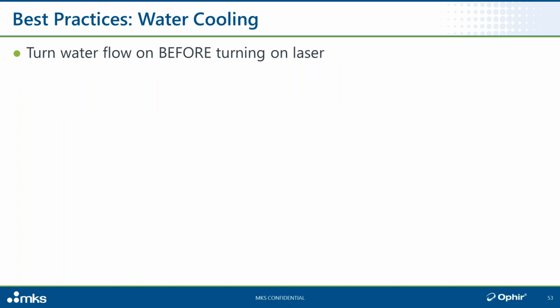Some really important tips with water cooling, and then we're gonna summarize. Very, very important, and we've learned this from a lot of bitter experience of our own and of many of our customers. Turn the water flow of the cooling water on before you turn on the laser.